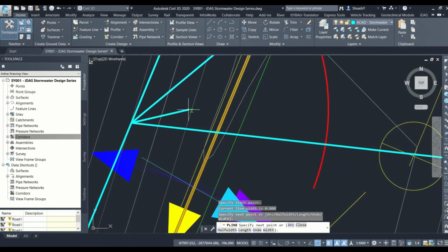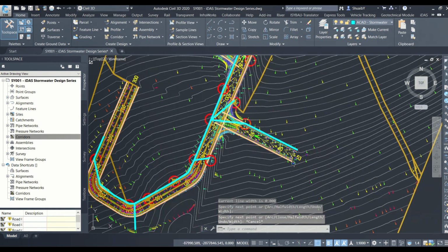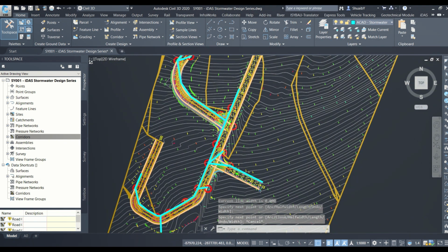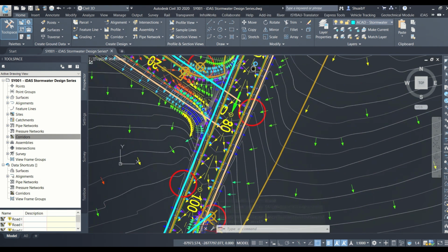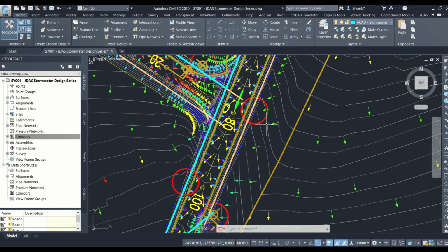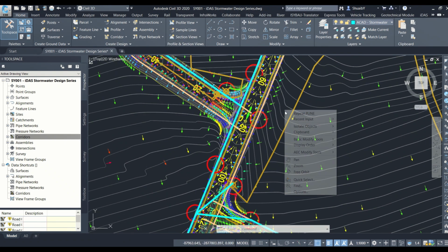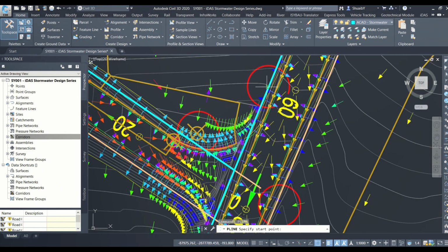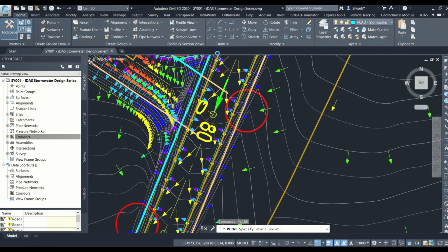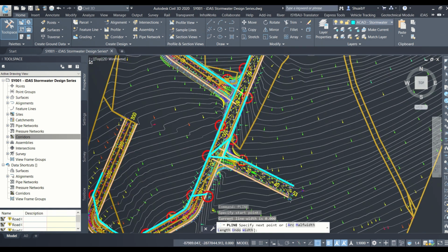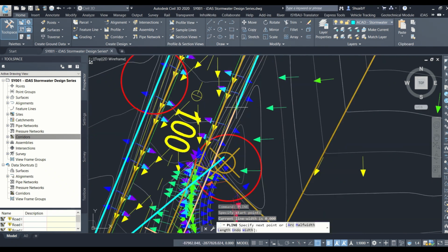And over here we're gonna also tap in there. You can see that we're linking it, but there's no vertices, there's no square grips there. There has to be a point or a vertex there so that a junction can be dropped in or a structure can be dropped in. And as you can see, we've got this one more here. I'm just gonna join this to this one.